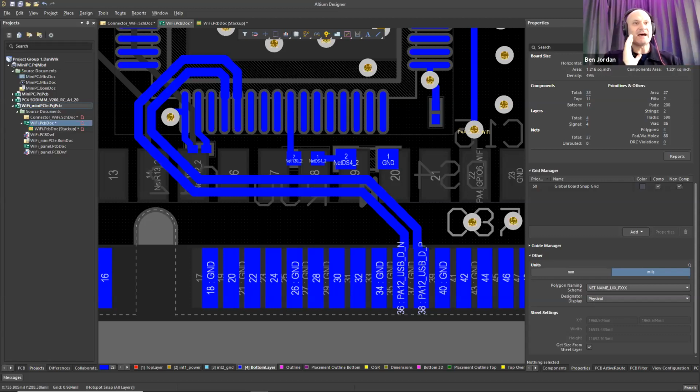You can make a 100 ohm transmission line on a PCB that has a 5 mil gap, and then scale it up and use the same relative dimension transmission line for a high powered RF amplifier, but with a thicker substrate, and the traces will be much wider. And you want that because you're going to be carrying some pretty heavy currents. And so, yeah.